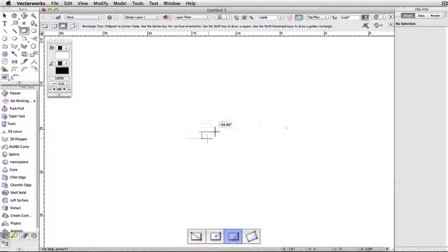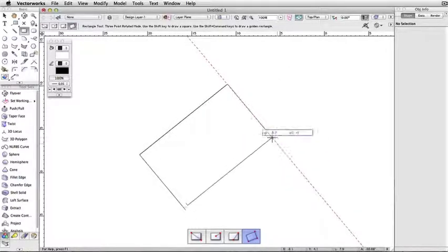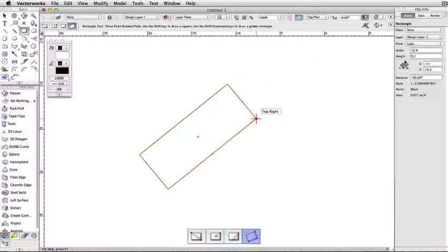Midpoint to corner mode sets first the center of one edge of the rectangle, then the second click will set the location of an opposing corner. The fourth and last mode will create a rotated rectangle. The first 2 clicks set the direction of one edge of the rectangle, then the third click sets its thickness away from this edge.